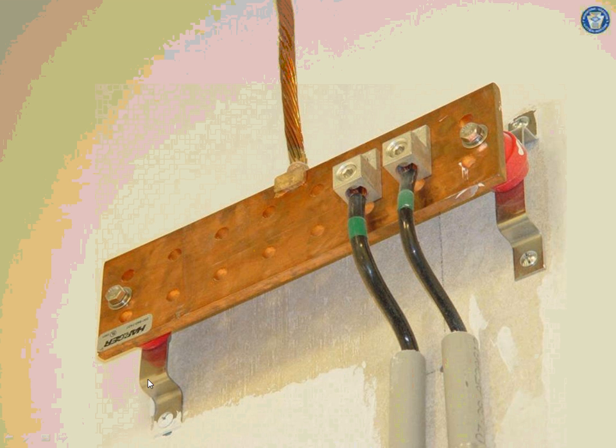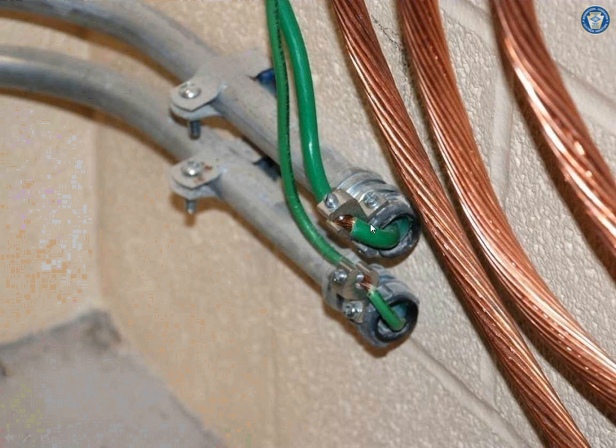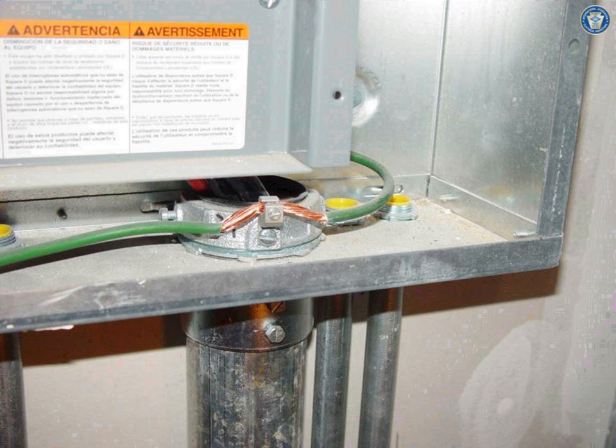Here's the bar that I was just talking about in multiple buildings. This could be coming from the ground rod or from the steel of the building. This is going to the generator of the service. You guys have probably wired or designed a few of these. If you protect your grounding electrode conductor with a metallic conduit, you have to bond it too. You guys have seen that one. The code says you have to bond it if it's a grounding electrode conductor. Or, as a matter of fact, an equipment grounding conductor, you have to bond it too. Here's bonding the conduits at the service.